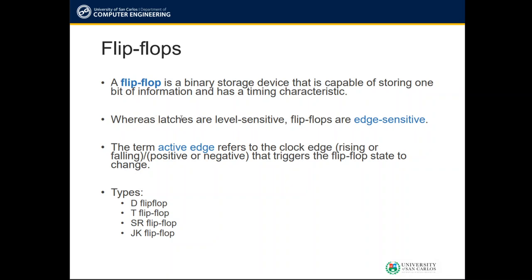The difference between latches and flip-flops is that latches, based on the previous lecture, are level sensitive, and flip-flops are edge sensitive. What this means is that when we create the timing characteristics, we look at the transition between 0 to 1 or 1 to 0, and determine what the differences are.